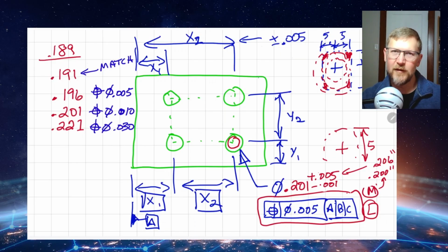If you're hand drilling and locating components, you probably don't want to go any tighter than 30 thousandths. A CNC machine might be able to hold 5 thousandths, but a person trying to locate and drill something by hand is going to have a much harder time. So if you can specify a much looser hole, that gives a lot more flexibility to the installer. Instead of needing a $1 million CNC machine, now I can send a tech out there with a hand drill, right? So that's how these tolerances come into play in terms of manufacturing costs.